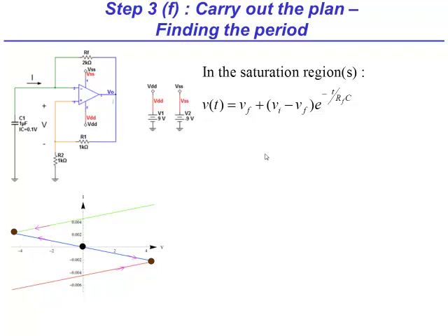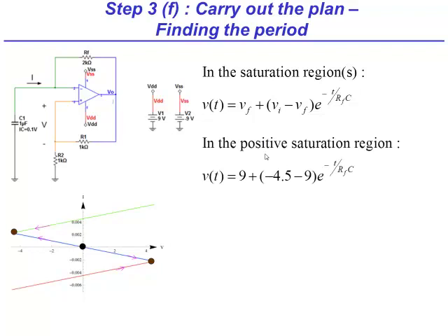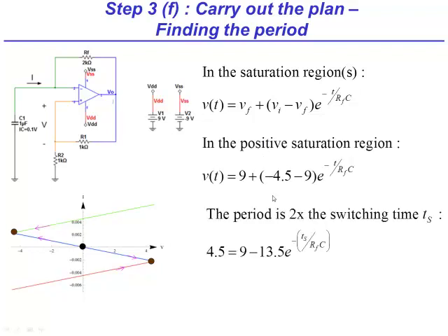No worries. I will simply compute the time the circuit spends in one saturation region and double the result. Doing so, I find the period to be shown here. This is exactly what is derived using more complex techniques. Also, I can easily handle the case when R1 is not equal to R2. I guess we can now move to the lab demo.